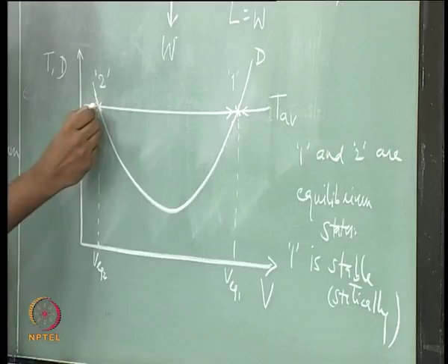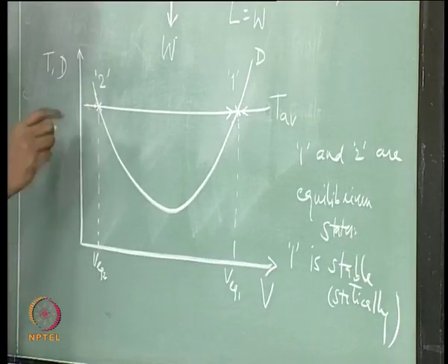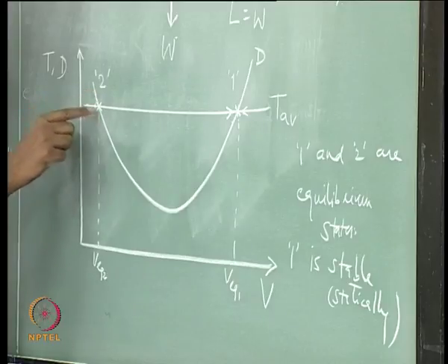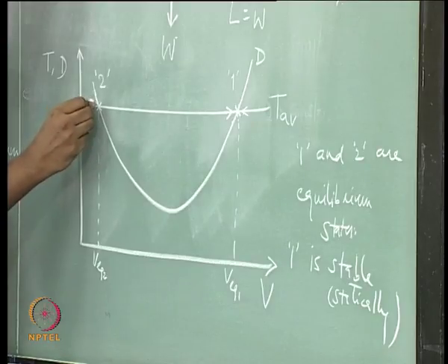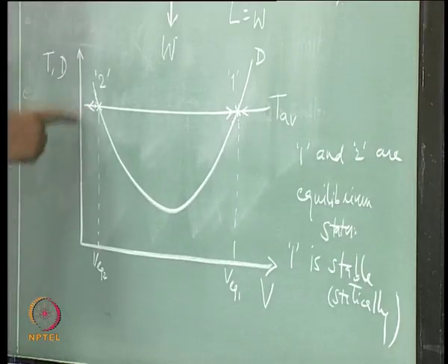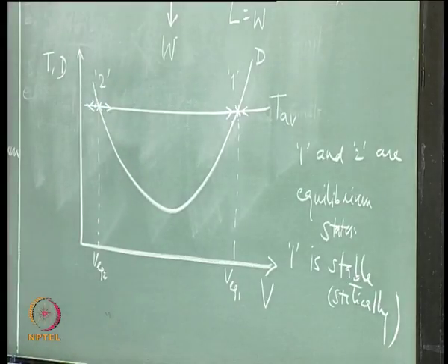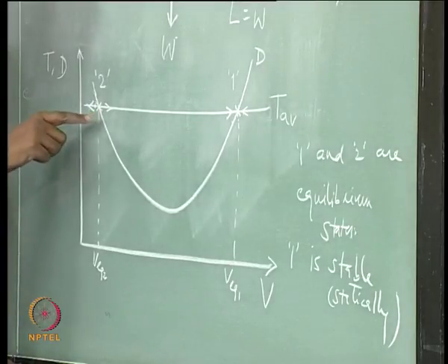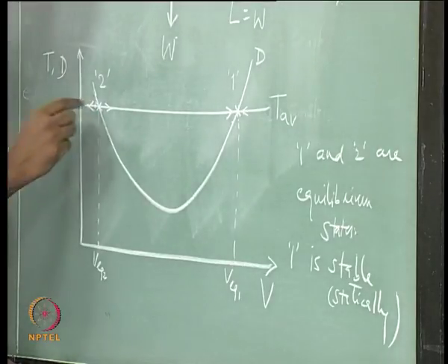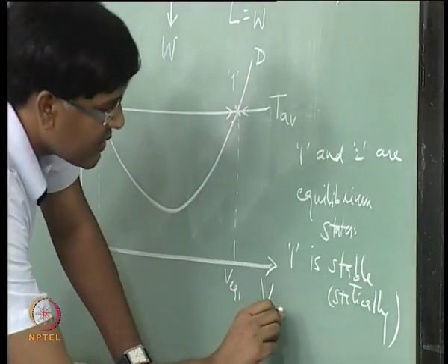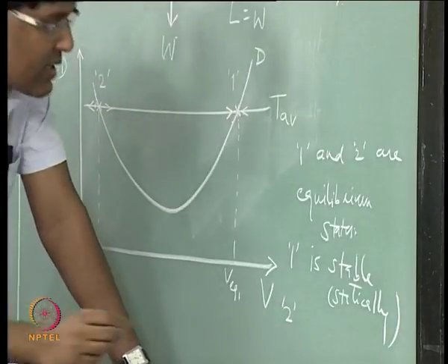So, if there is a decrease in velocity in this case, now drag is again more than the thrust available. So, aircraft will decelerate. So, it is going to take it away from this equilibrium condition, and on the other side giving the similar argument, the aircraft is going to go away from this equilibrium condition. So, this equilibrium condition is statically unstable with respect to the change in speed due to the disturbance.